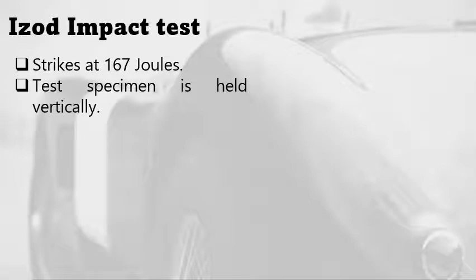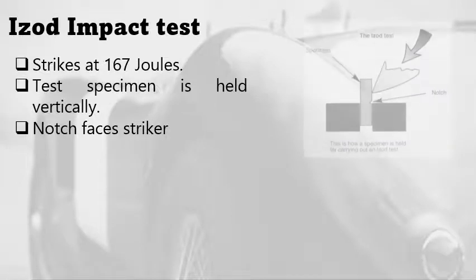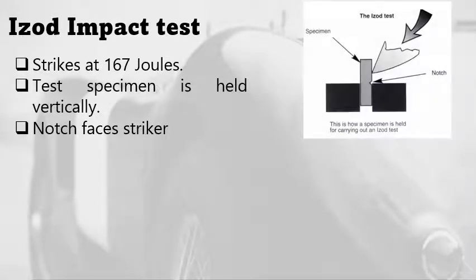Two classifications are described here. We have the Izod impact test. Here it strikes the material at 167 joules, and the test specimen is held vertically. The notch faces the striker. So you can see here how the Izod test is being carried out.